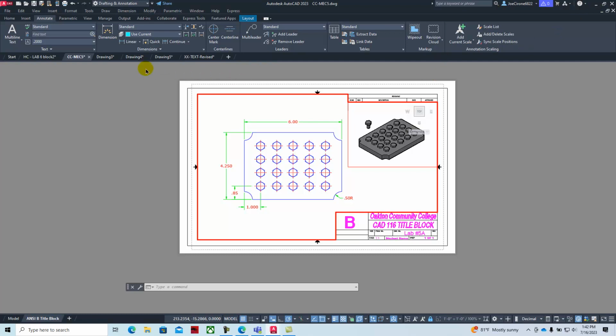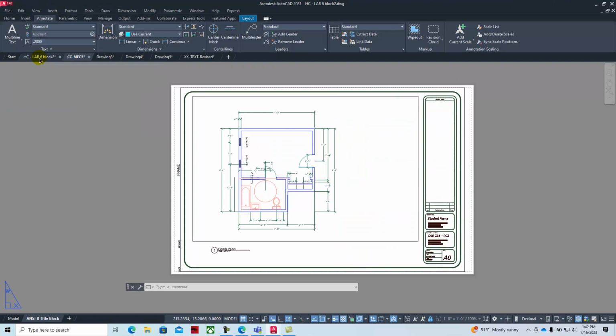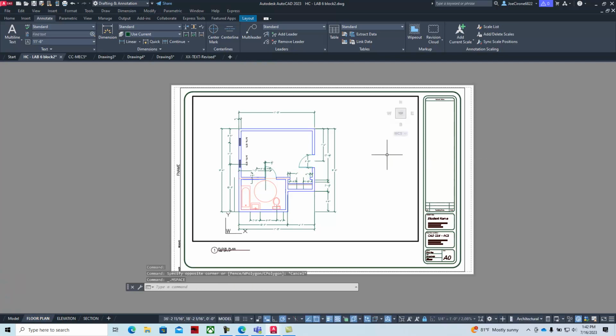Same with the architectural drawings. And so if we were on an architectural drawing, here's our viewport tab, or our layout tab. We're in paper space, and then if we double click in the viewport, we can see that this viewport is set at 1/4 of an inch equals a foot. And that's where we get into all these different settings for scaling, which we've pretty well set up for you already by using the templates.